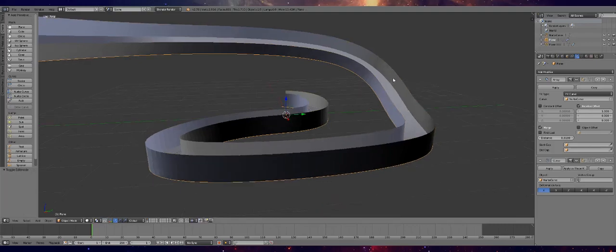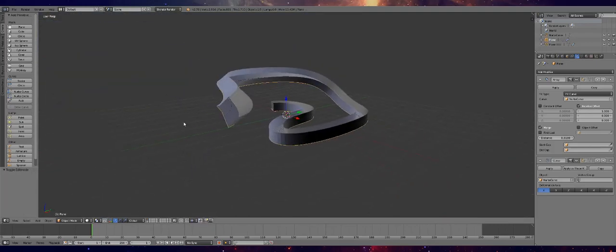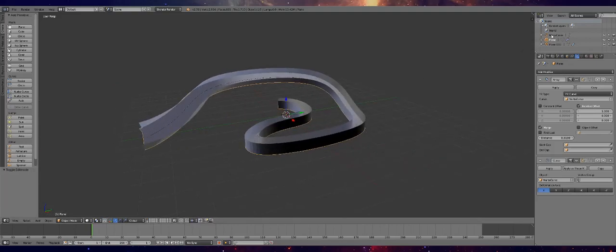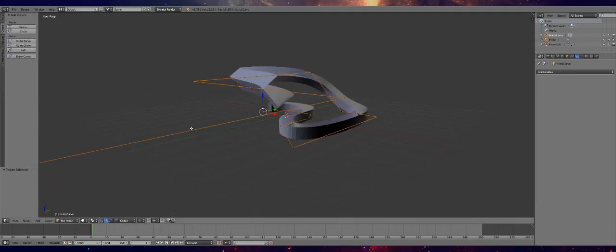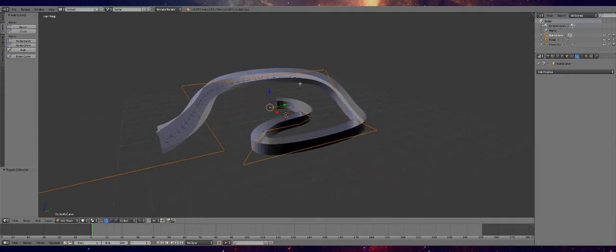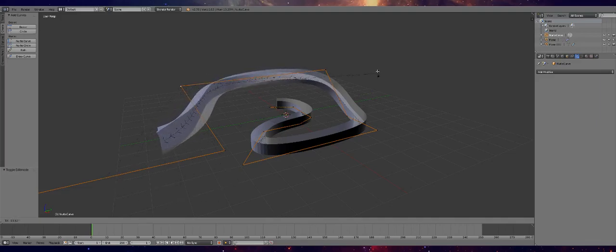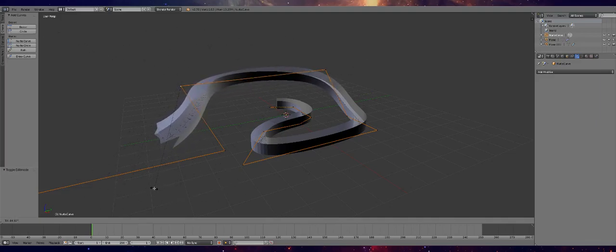So what I'm going to do now is fix the twist because our card can't handle these, and the way I do that is I select the curve, and all the points that I see that cause the twist, so this one is a specific one, I can go to it and press Ctrl T, and that gives me this little angle, and based on how much I rotate it around the point, that's how much twist it will apply. So I'm twisting it to counter the base twist, if that makes any sense.